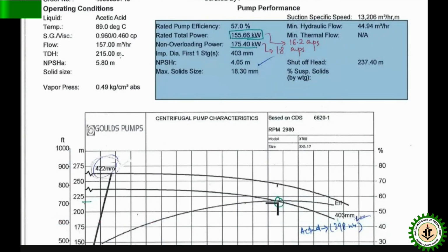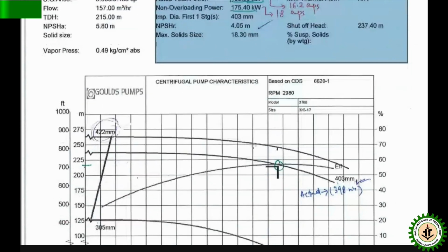Same way it is for the control valve also. If you want a control valve with certain flow requirements and pressure drop requirements, they will not design it for you. It's already available in the system. One of the models, you have to select. There can be revamping also. There are options, like port size up, CV up, these concepts are there. So this is the concept.